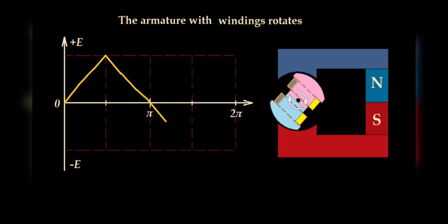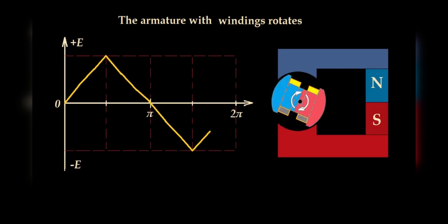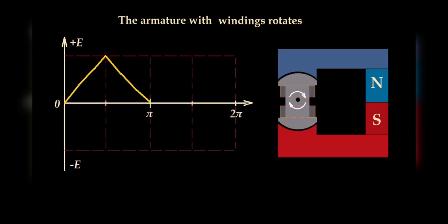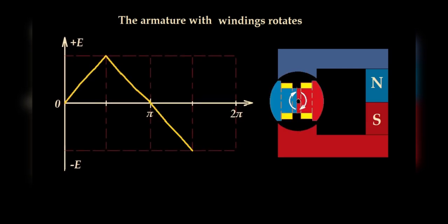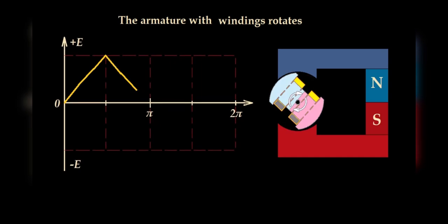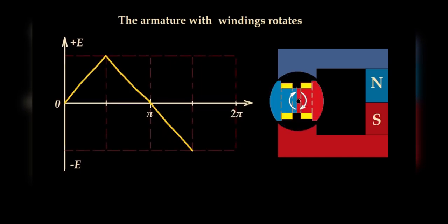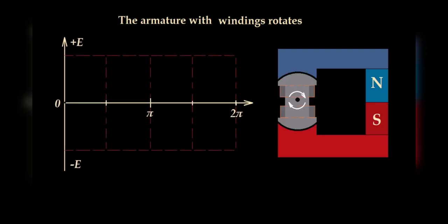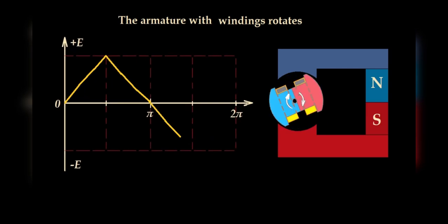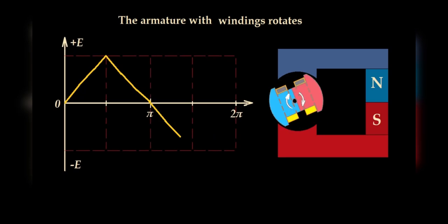With further closure of the magnetic circuit, the anchor pole has the same polarity as the pole of the excitation system. The excitation system begins to demagnetize the anchor, while the EMF in the winding decreases. When the anchor reaches the position of complete closure of the magnetic circuit, it will be demagnetized. Further movement of the anchor will be associated with magnetization from the excitation system with an increase in magnetization from the phase current. All these actions completely coincide with the synchronous change of electromotive force.